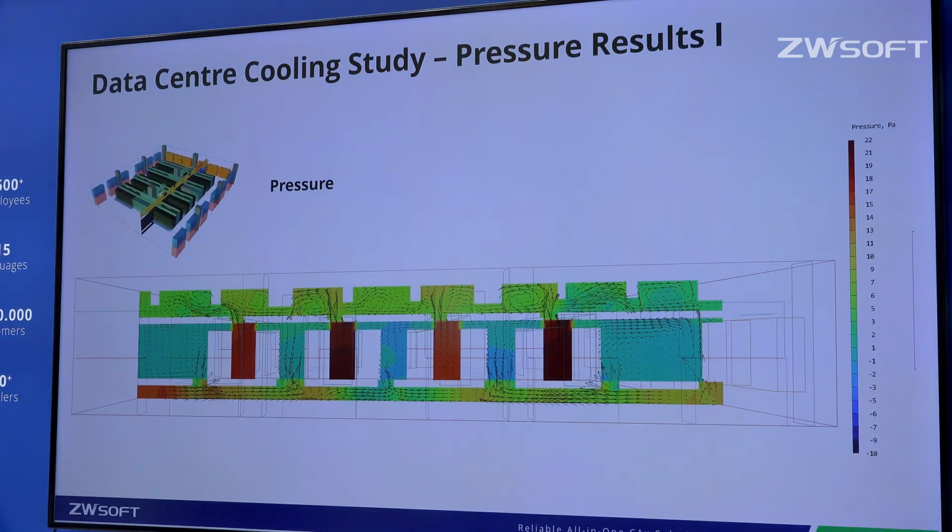So now with changing the slice that we're looking at, we're now looking at a side-on view of the room with a cut through all the servers. I hope in the little image in the top left you can see where this plane is located. Here we see the three zones of the model: the underfloor, quite clearly, the room, and the ceiling plenum. We can also see that the hot aisle containment is affecting the pressure.